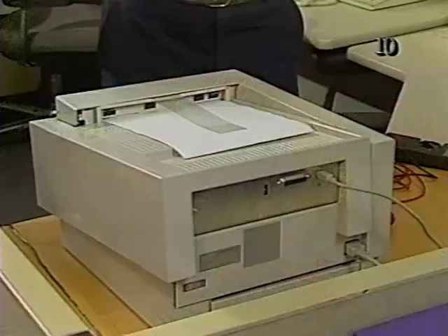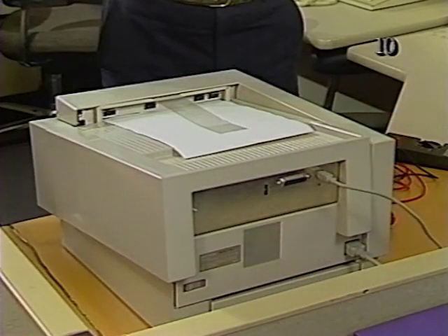Congratulations, you've isolated the fault. The laser is not receiving the correct voltage needed to function properly. To fix the personal LaserWriter, the DC controller PCB must be replaced. After replacing the DC controller PCB, but before reassembling, be sure to perform preventive maintenance. When the personal LaserWriter is reassembled, set up and operate the LaserWriter.